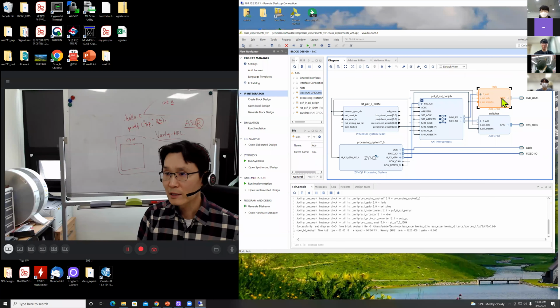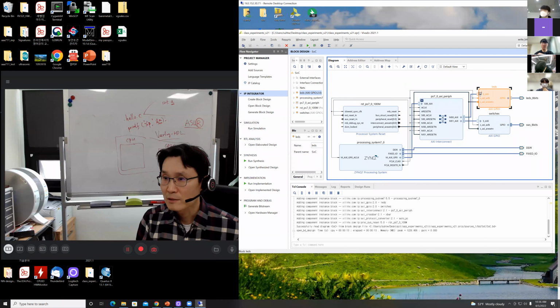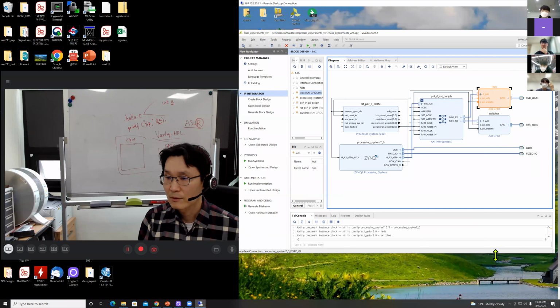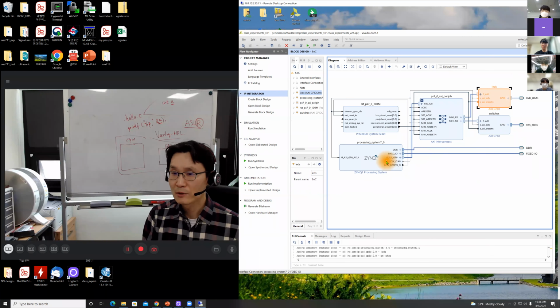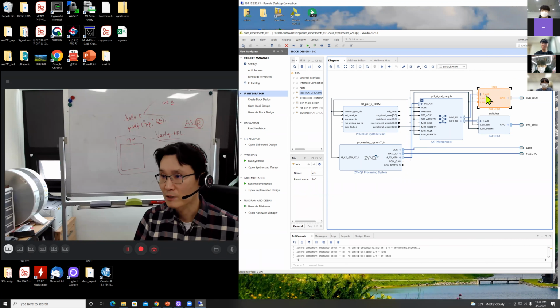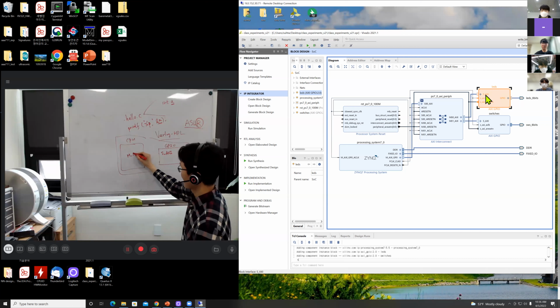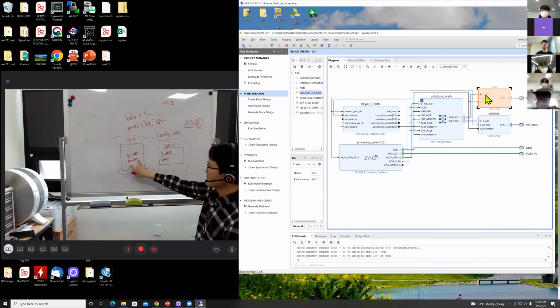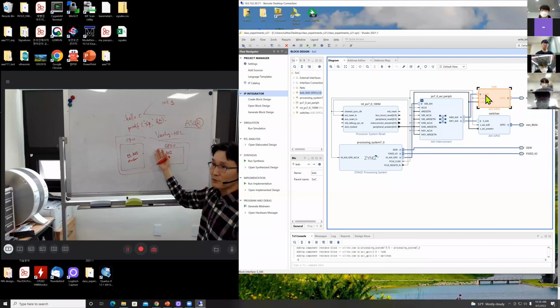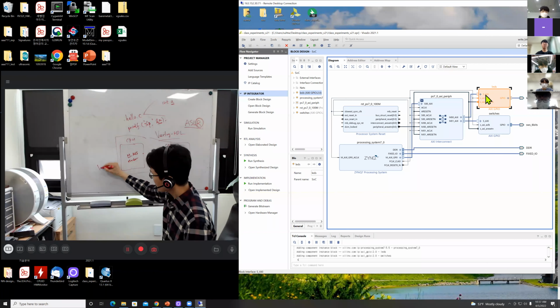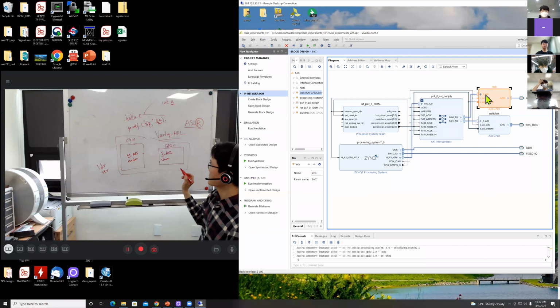Okay, so that is the LED GPIO and the switch GPIO. Expand this. We have a connection from the CPU to the IO device through the slave AXI protocol. The CPU provides the master AXI protocol, master and slave. The master generates transactions, the CPU. If you execute LDR or STR, a memory access, it generates a transaction, and the slave responds to that transaction.